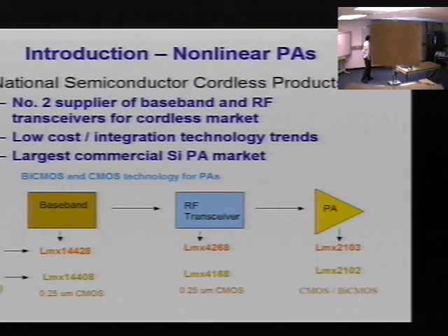And again, we're trying to be very sensitive to make sure that they can relieve pressure on the design of their driver to go down below 0 dBm, even though they could spec at 2 dBm on the driver coming out. The thought was to have very good power gain on the PA at 26 dBm, and to look at a CMOS and a bi-CMOS process. And these were the names of the products that National has in both of those bands.